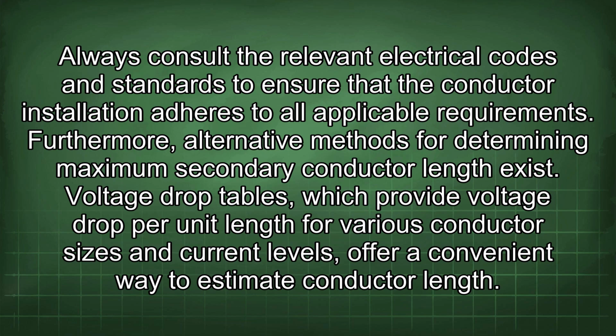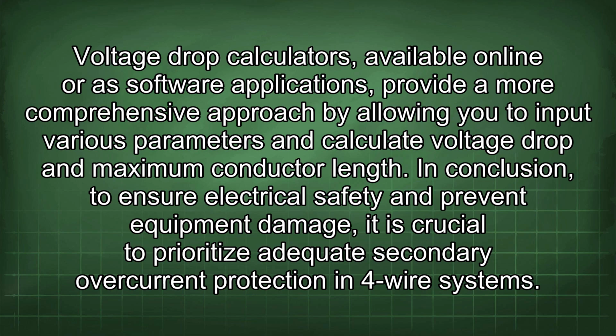Furthermore, alternative methods for determining maximum secondary conductor length exist. Voltage drop tables, which provide voltage drop per unit length for various conductor sizes and current levels, offer a convenient way to estimate conductor length. Voltage drop calculators, available online or as software applications, provide a more comprehensive approach by allowing you to input various parameters and calculate voltage drop and maximum conductor length.